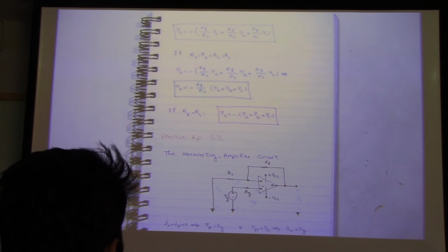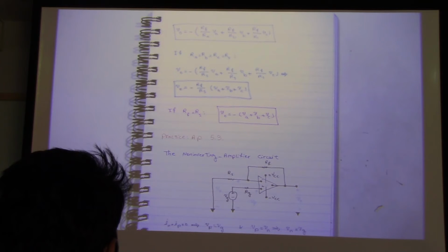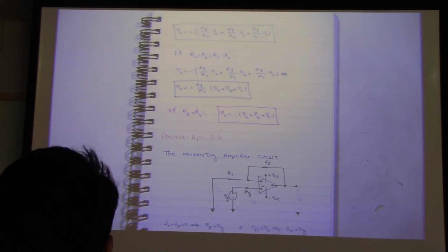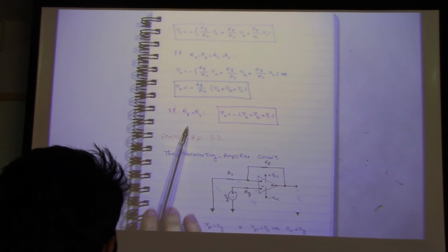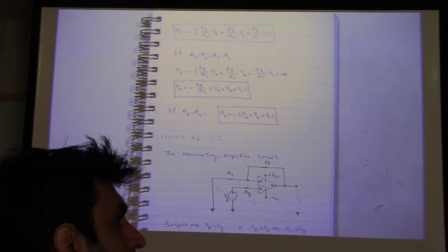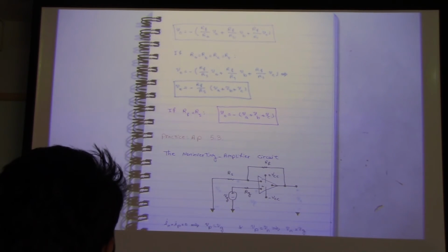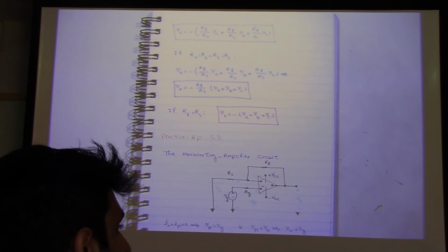Does RF always have to equal RS? It should not be always like that, but we assume if they are equal, you get this. Even if they are not equal, again it is the summation, but you have to multiply by a scaling factor, which depends on the values of RF and all input resistors.